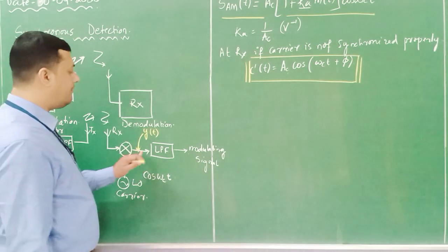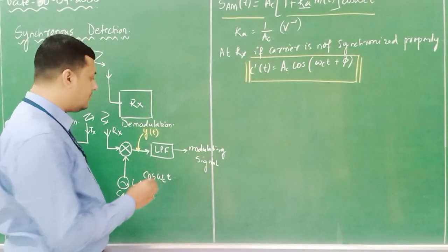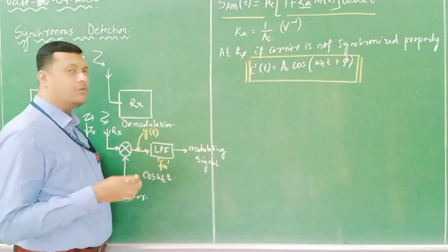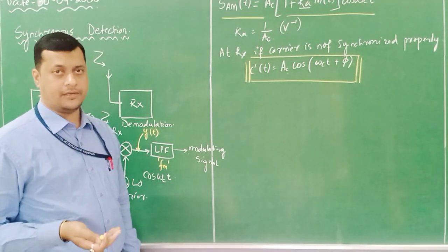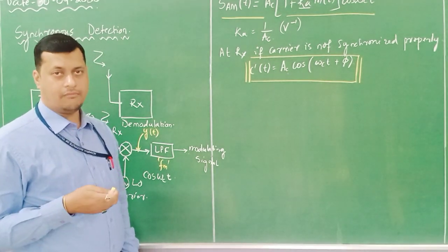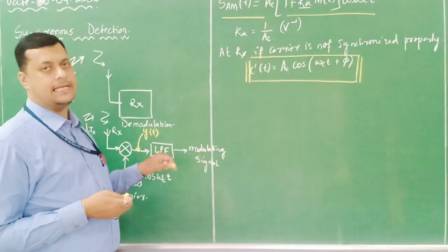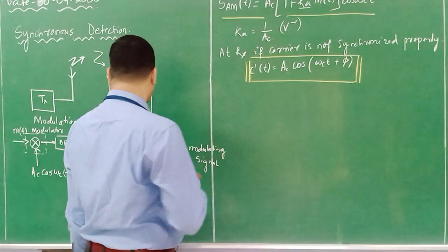And then y(t) is fed to the LPF, which is centered at the modulating frequency fm. It will remove all the harmonic components, the higher frequency components, the carrier frequency component, as well as the DC component, and then we will see what our modulating signal is.